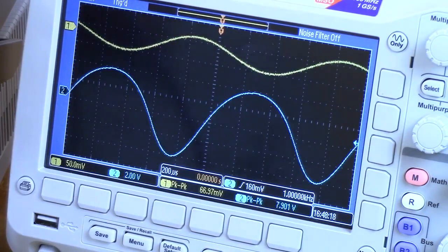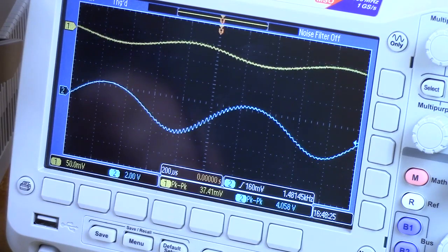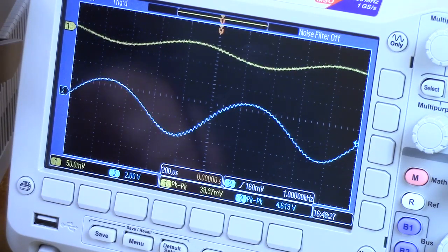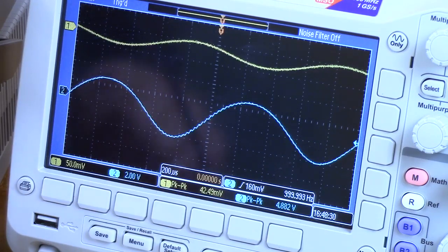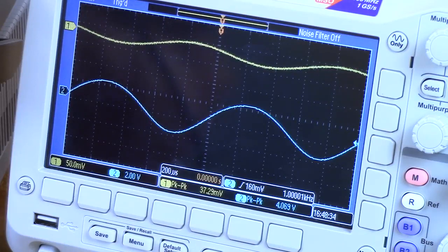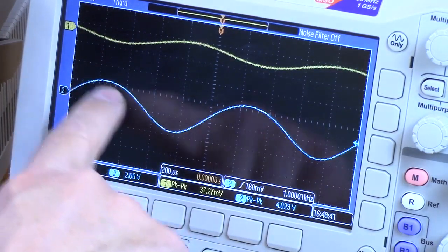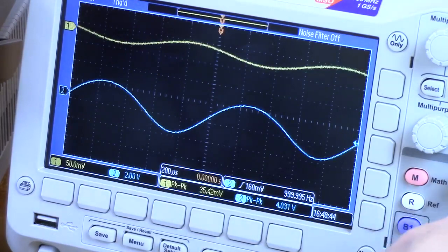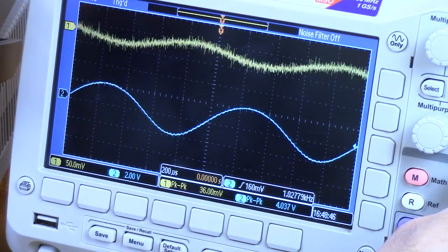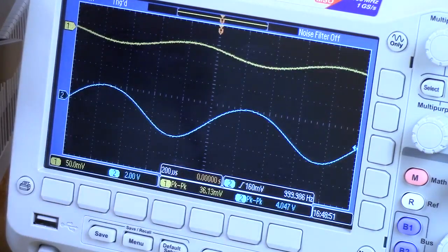Okay. Now we're going to bring the pot up in value until that output signal gets cut in half. We do have some oscillations in there. Not sure why that is. You want to turn off averaging? I think it's better to leave it on and get the waveforms clean. So right now the output is 2 volts peak to peak. We can slide this down. And it goes from there, 2 divisions there. So the signal's been cut in half.